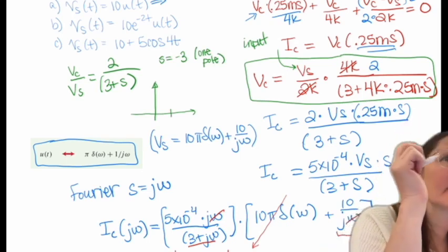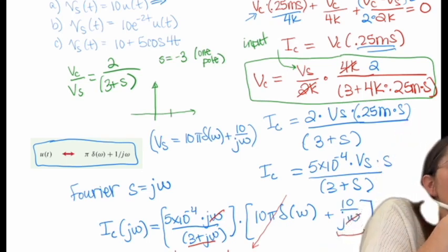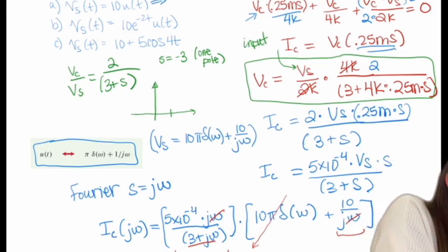So, yes, it's a low pass filter, and so it would go out around 1 or 0 decibels, and then it goes out to a frequency of around 3, our corner frequency, and then it goes down about 20 decibels per decade after that. If we go a linear approximation, this would be down at -20 dB per decade slope.